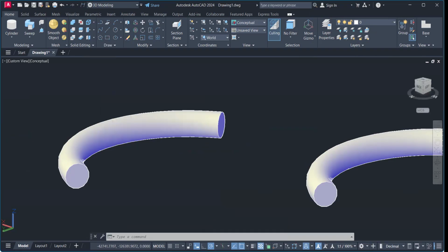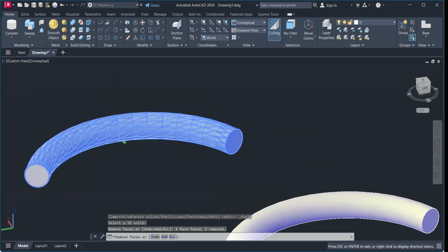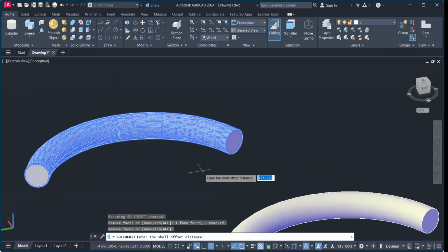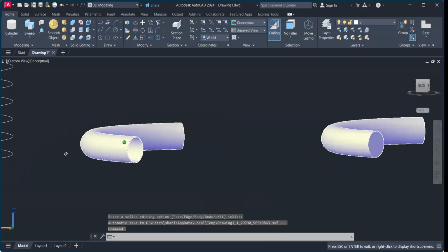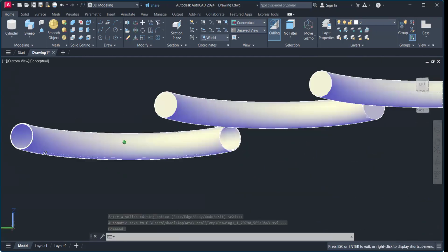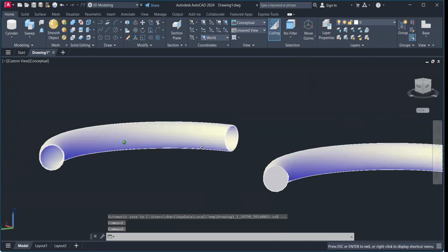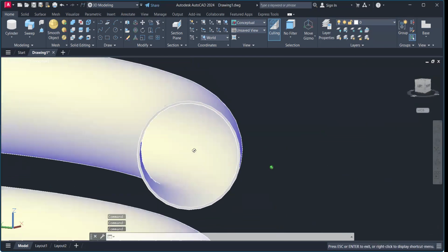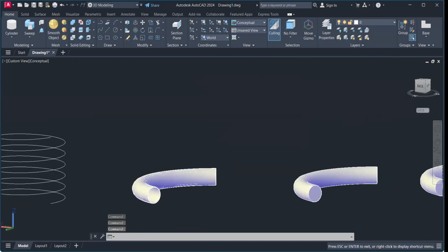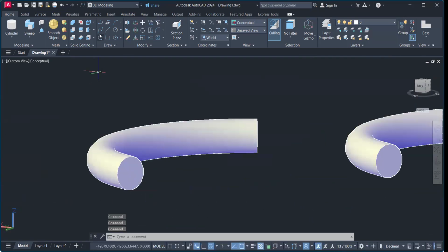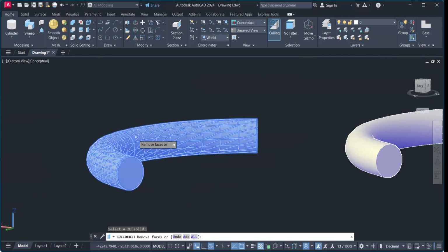This is my 3D solid. Then next we click the faces first. All the faces, first and second ones here, then enter. Then shell, enter, offset distance I take as 1. And then once we get here, we got this type of hollow portion. By this way you can make this type of hollow portion. Is this clear? This will be shown like a hollow. If we again talk about shells inside this, first of all select the shell, select our object, and then without hitting enter here, just click on this face.